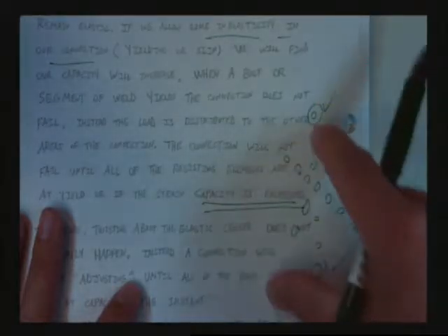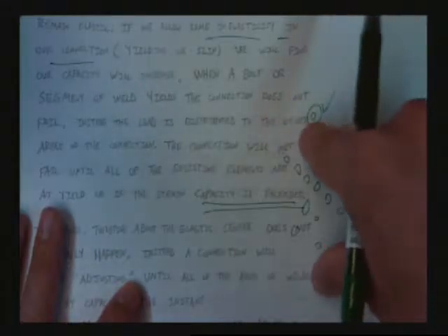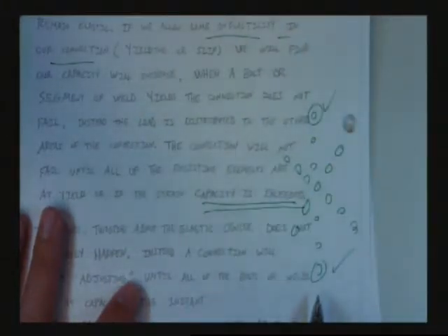Then you may be able to draw it up in AutoCAD, do some kind of rotational analysis, and see how much rotation you think you're going to need. And then you may need to back calculate and see what strains that'll be placing and see if you're within the allowable limits. Or you can just do the elastic analysis, the old school one. Remember the one we just did qualitatively here?